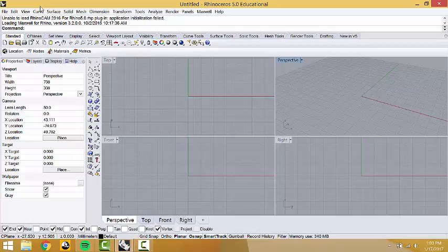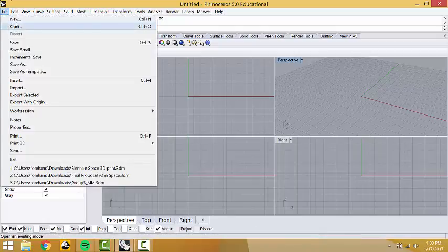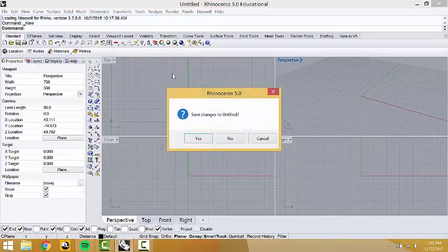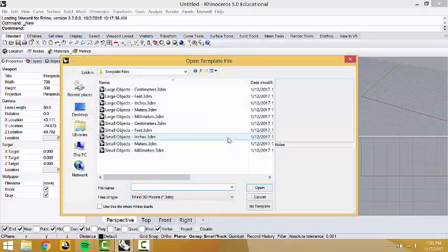Like many other modeling systems, the units are based on numbers, and they don't care if it's an inch or a centimeter or a millimeter. It is one, and you change the name, and it doesn't care. So the first thing you always do is confirm your units. So file, new document, we'll just show you what pops up, is this.